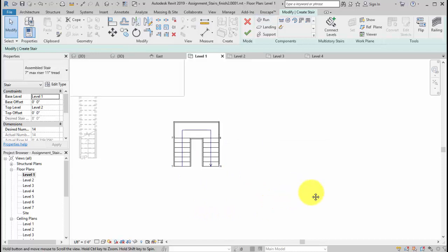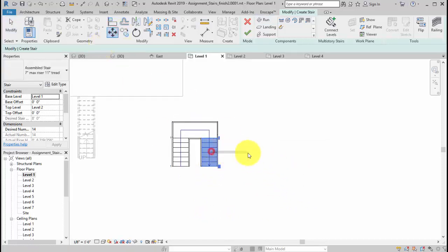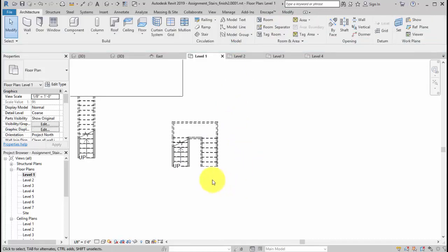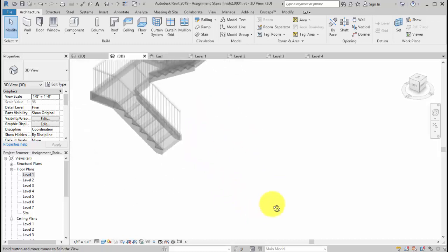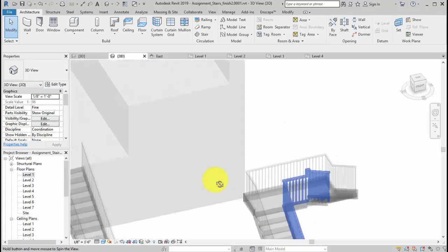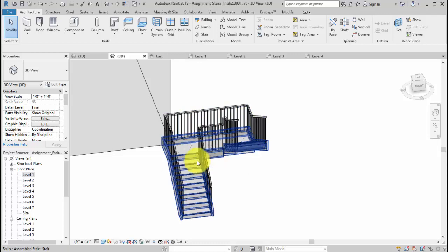Don't really have to worry too much about it, because after you finish it, you can still change the stair, somehow move around the staircase if you want to. We can modify all the parameters later if you wish, but we're going to finish this because this seems to be perfect. 3 going up and go through the landing, another 3 going up, so we split this in 3, and this will be a perfect U stair with 2 feet in between.